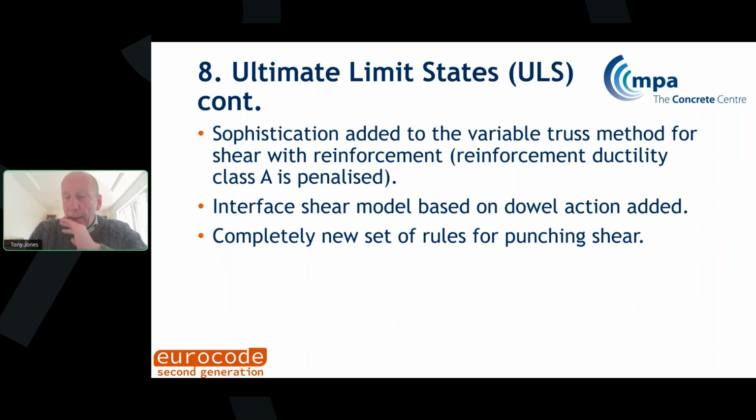Interface shear, previously it was purely a friction model, so you calculate the tension across your interface, and that gave you a friction force to take in interface shear. That model has been enhanced, but there's also been a new model which can be used based on the dowel action of the reinforcement crossing the interface, which is very handy if you've got a small embedment depth, so you can't actually anchor completely the tension strength. And there's a completely new set of rules for punching shear.